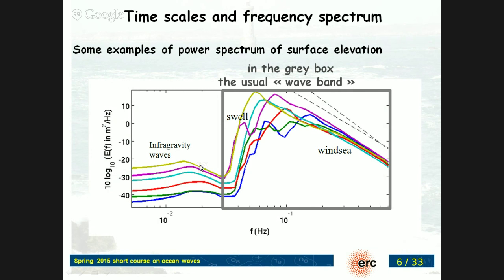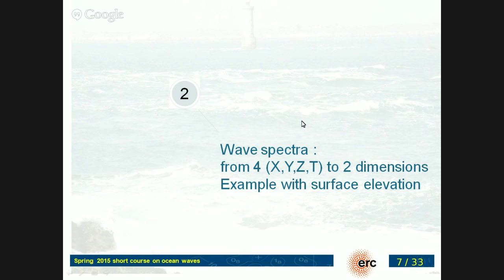Usually in deep water, it's much lower. So you're talking about a 30 dB difference. So in deep water, this is negligible for most applications. But in shallow water, it can be the other way around. This peak on the beach is actually often higher than this one. So if you're measuring in 1 meter water depth, you can expect to have a very big peak here compared to this one. All right, and so the wave motion is not just the elevation.